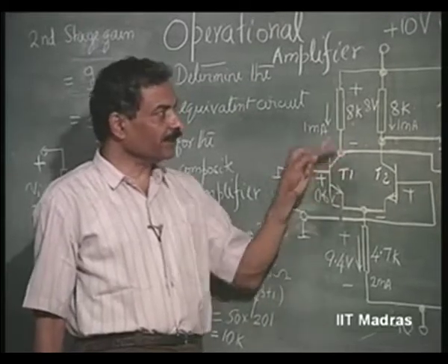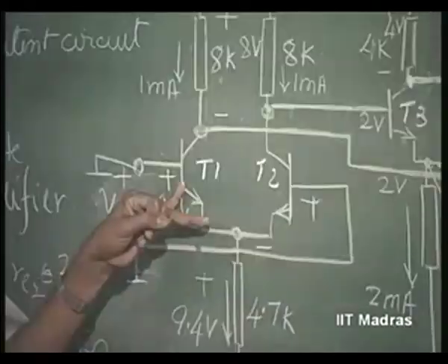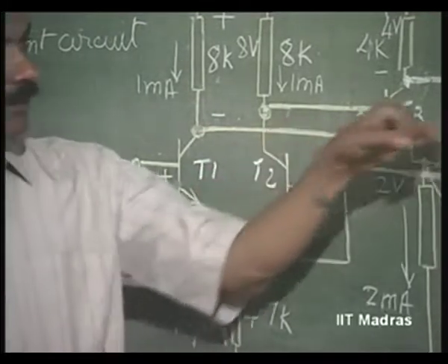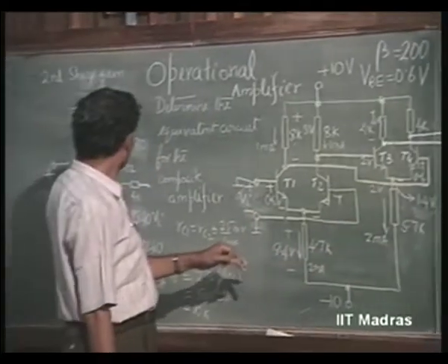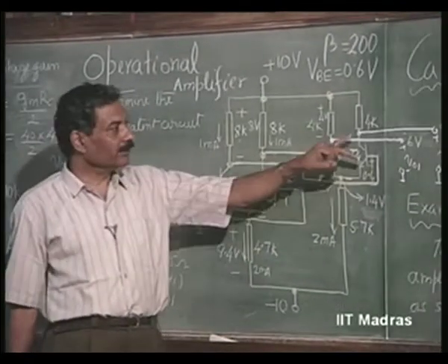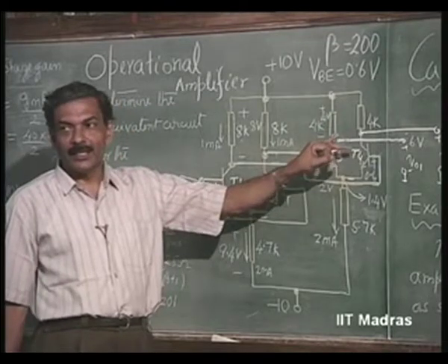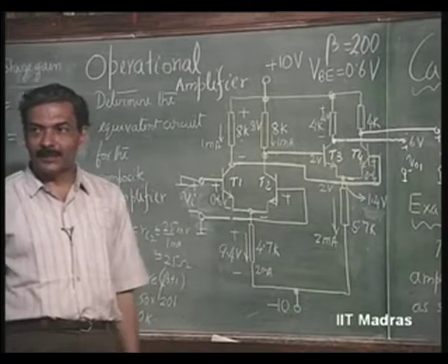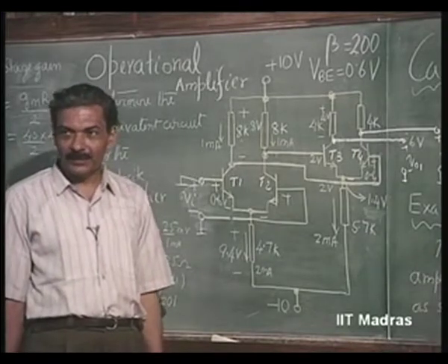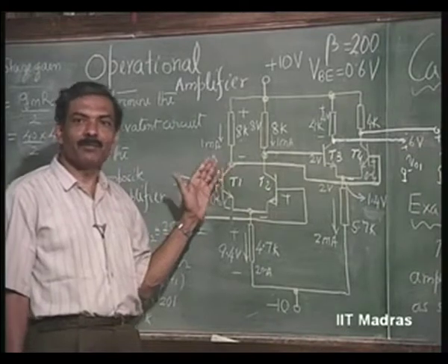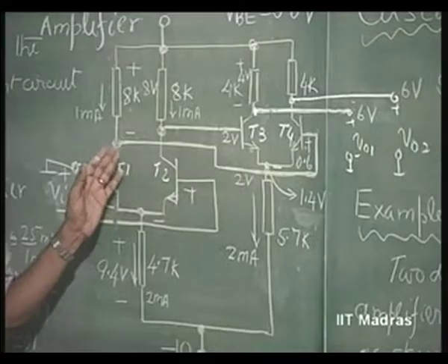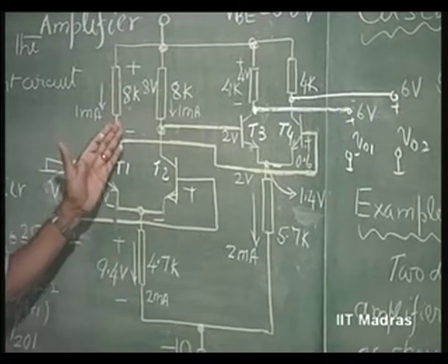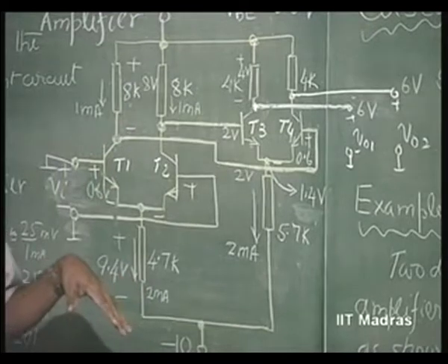That means, this can give you a swing of 2 volts, but that much swing is not needed, because the gain of this entire structure is going to be of the order of 80 or so. So, even if you consider 8 volt swing, 8 volts divided by 80, that is the voltage swing that is required at this point. You are providing a considerable amount of reverse bias unnecessarily. Again, this 2 milliamperes into 8 k is not at all needed here.